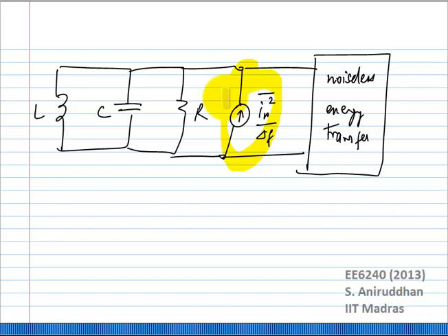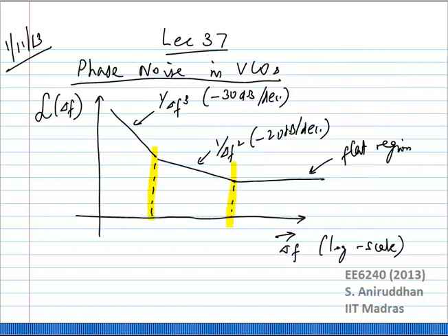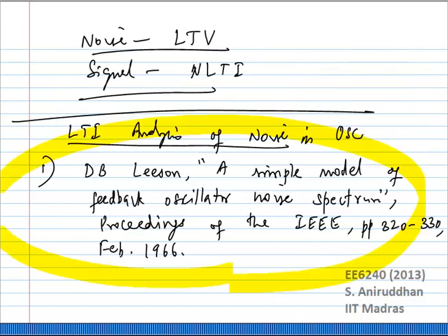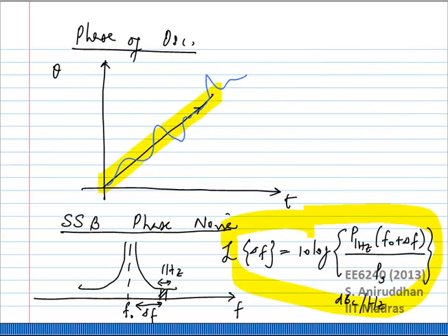It's perfectly okay to just take the noise power and take it down by half, because the way phase noise is defined, you are defining it with respect to the signal power. So there is really no problem with dimensionality as such, as long as you take noise power and compare it to signal power.